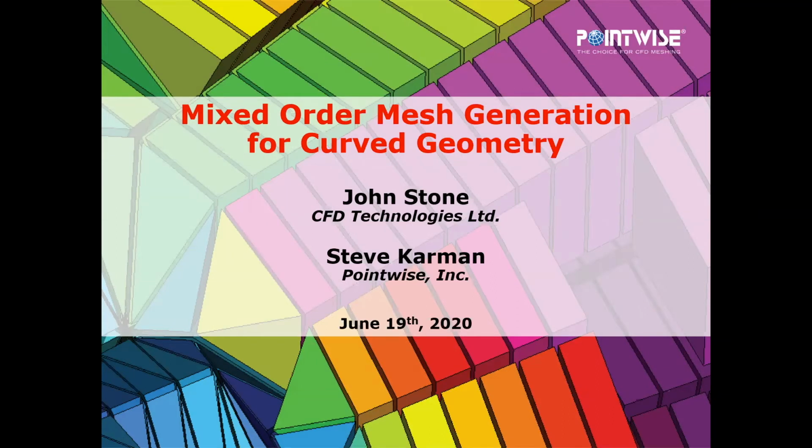The linear mesh is elevated to the required degree on an element by element basis in regions of high curvature. Several three-dimensional examples are going to be shown that demonstrate the effectiveness of this method to produce high quality mixed order grids.